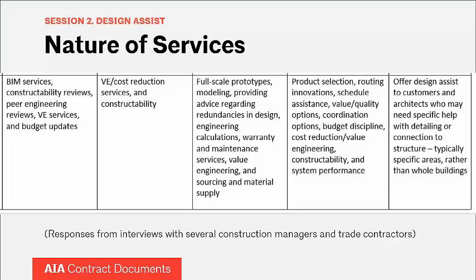And this is one of the main differences that we identified between design assist and delegated design. In design assist, the contractors and subs are providing input about things like installation, constructability, job site logistics, scheduling, and so on, construction related input. In delegated design, the contractors are going to be providing professional design services, often through a second licensed design professional.